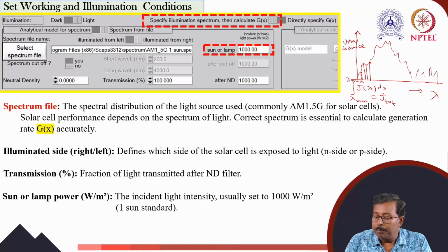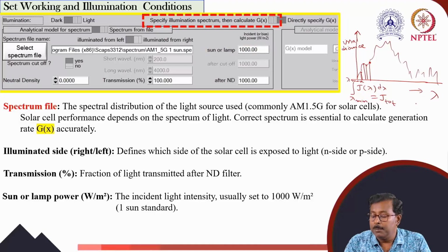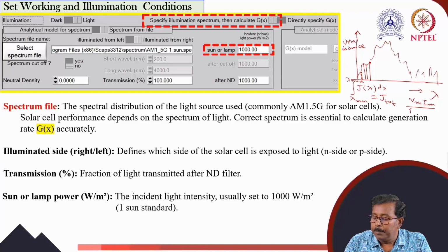Okay, but in the formula for the power conversion efficiency, there is Vm into Im by P incident. This P incident is the optical power, and this is volt into ampere. Volt into ampere means volt into coulomb is energy, and coulomb per time is the current. So volt into ampere, this gives you also watt. There is a rate of change of energy, that is joule per second or watt. So this watt is the electrical wattage you are generating, and this is the input wattage applied.